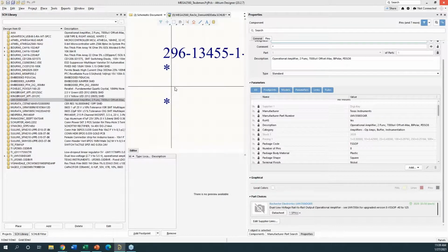It doesn't give you the model, which I think is kind of silly, but I think at the same time, this is Altium's incentive, saying, well, if you want the model, then you can acquire it, and you can acquire it through Concord Pro or Altium 365. So I think they did that kind of on purpose, that they'll at least get you all the parametric data, but you've got to create the model yourself. So just be aware of that.